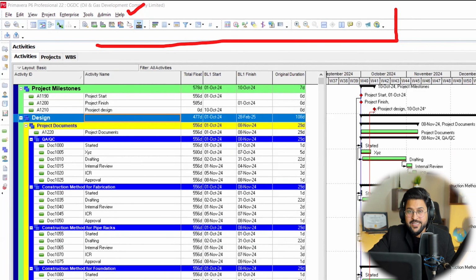Whereas the site work area, like this one, you can see right now, site work. So these are the major WBS. You can take these WBS from your BOQ, and the BOQ will be taken from the design. This is the hierarchy of your documentation. But as of now, I just want to focus on how to use these documents and compile your project. So this is my higher level WBS. I need this WBS to load within my Primavera P6, but for that, I need to create a new project file. So here I am.